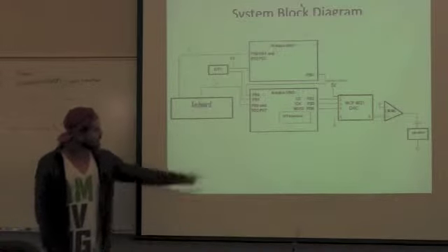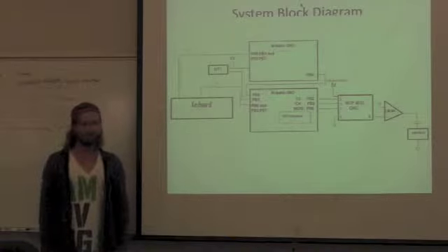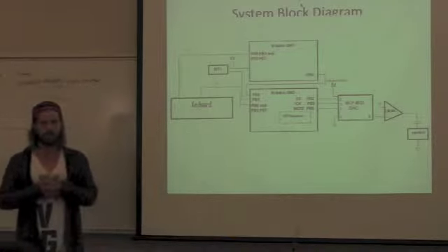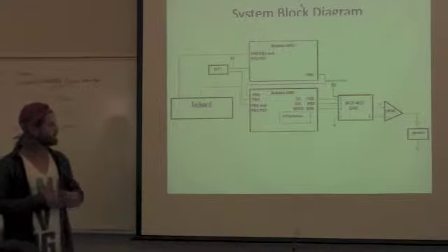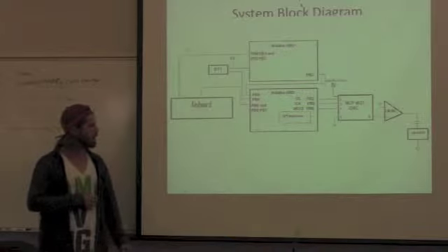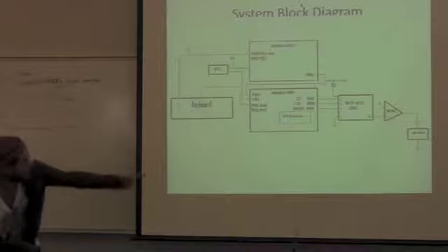And then right out of there we got our DAC, pretty similar to the function generator. We ended up using a square wave. We wanted to use a sine wave, but we'll get into that later when we go into the integration and testing. And then there's our op amp right there to amplify, going into an 8 ohm speaker.